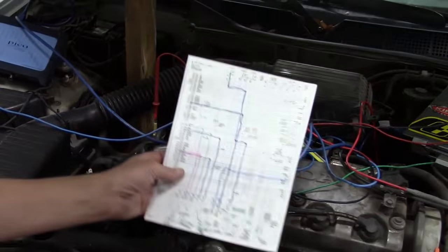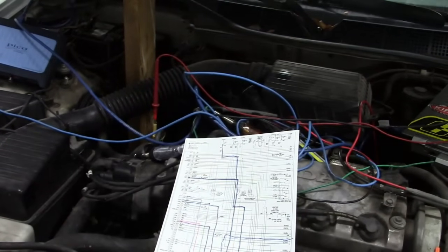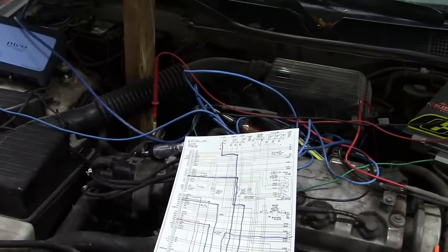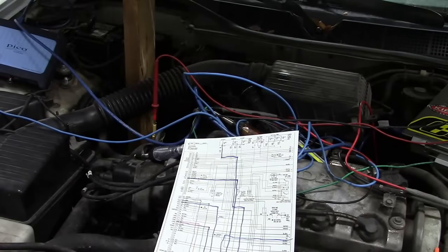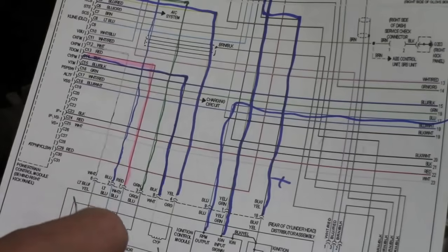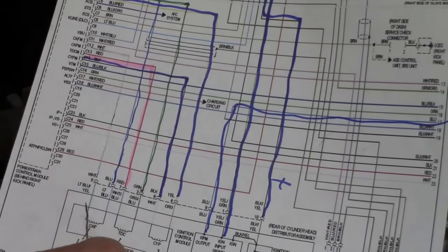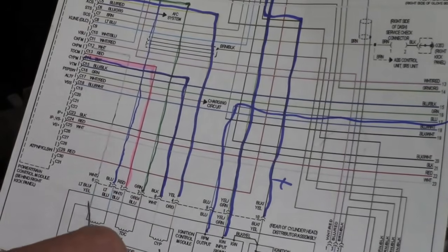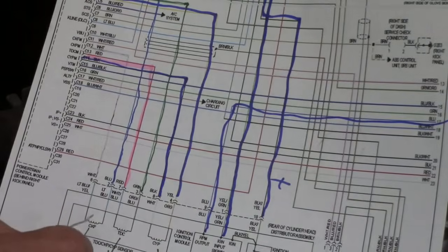All right, so now what we're going to do is the same thing, but on one of these sensors. And I know that these sensors are going to work. We've got the crankshaft position sensor. If we look on our wiring diagram, we've got our 2-wire sensor. So we are not expecting this to be a Hall effect sensor where we would see a square wave. We are expecting this is going to be more of a sine wave type signal. It's going to produce an AC voltage. And we, again, can do the same thing.